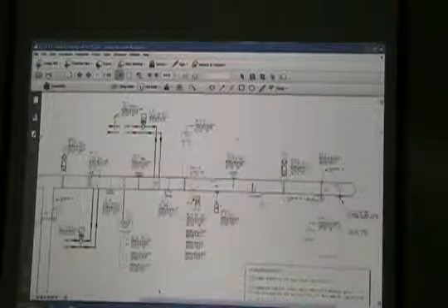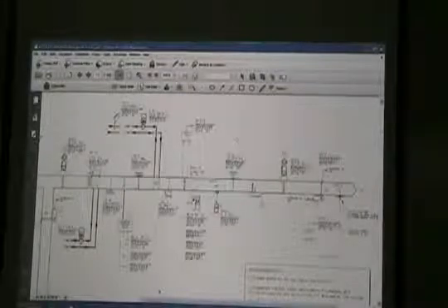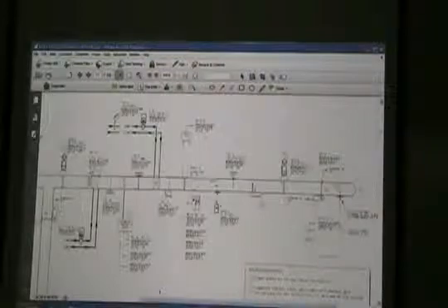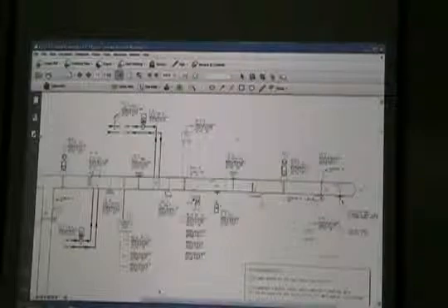If you look at the next page, chill water valve shall be modulated in sequence with the preheat control valve as required to maintain supply temperature set point at 55 degrees. In the event of a low limit alarm, the chill water valve shall be fully open. So we talked about that last week, the low limit, this low temperature detection device right here. Part of that device is a switch. It's hardwired to the drive.